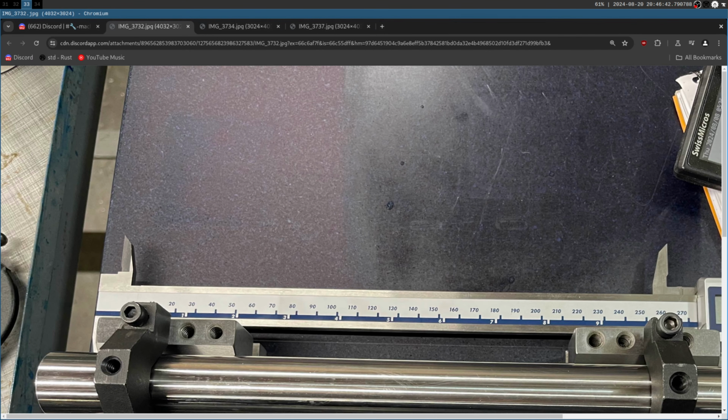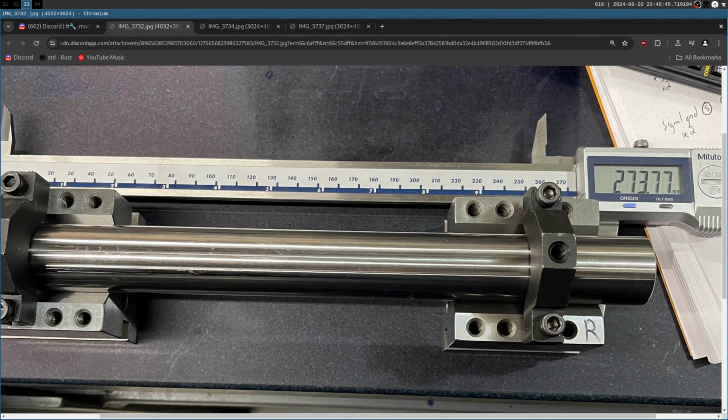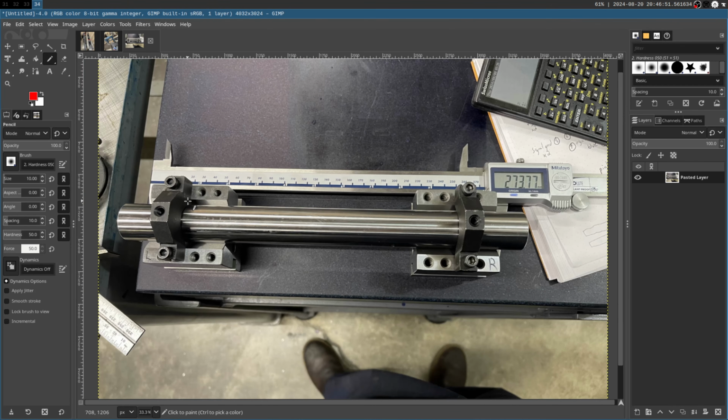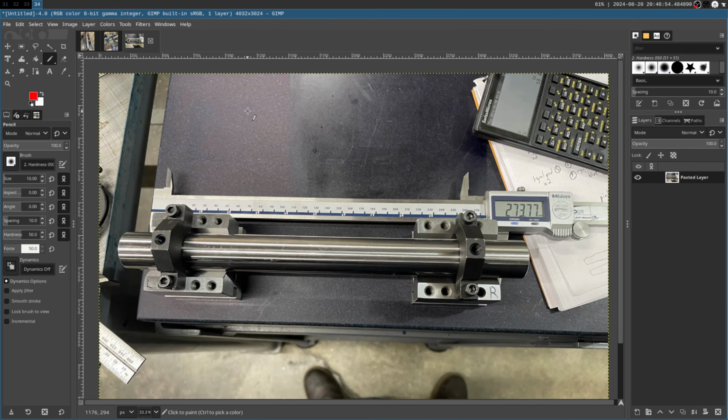So, luckily, it's very common in machinist shops, and thus in my shop, to have these, which are called V blocks, right? This is basically a block of hardened steel that looks like this, roughly. This allows you to set a circular piece of material in that V block. That's all it's for. Now, these V blocks are a matched set, and they're brand new. So these are very nice.